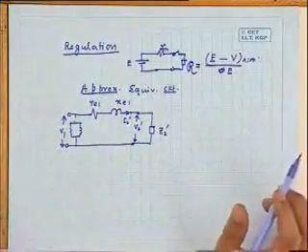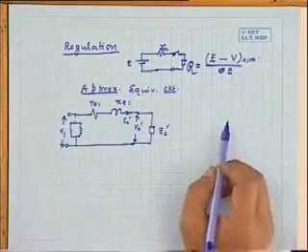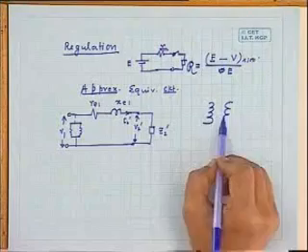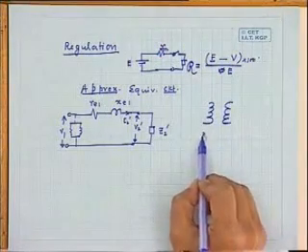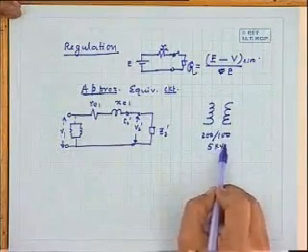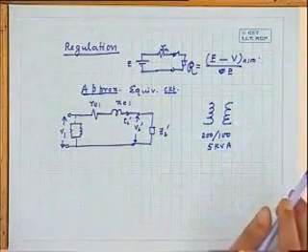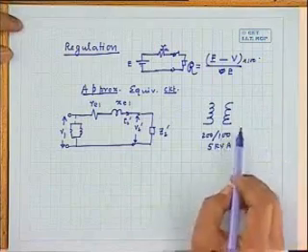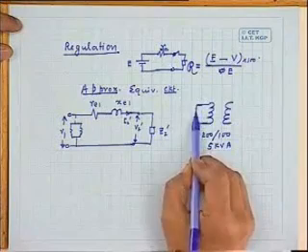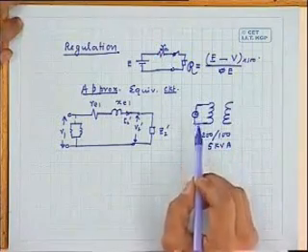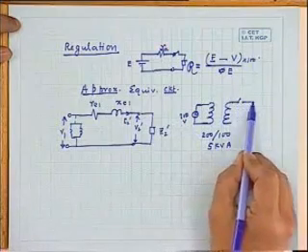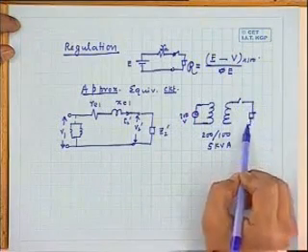Now, first, before we refer to this equivalent circuit, let me tell you how you measure regulation. Measurement is very simple. Suppose a transformer is given, whose rating is known, say 5 kVA, 200/100 volt transformer. I want to find out its regulation. What should I do? I will energize this with 200 volt supply.